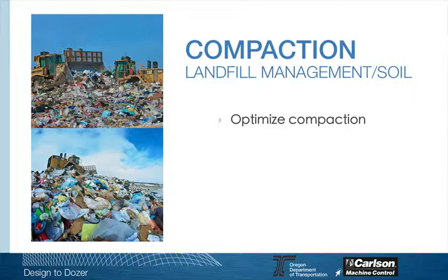Here on the left we see a landfill, and one of the first things that you can determine is that if I am moving a machine back and forth across material, be it trash or soil or whatever, I need to be able to measure how well I am compacting, and I want to reach optimal compaction.